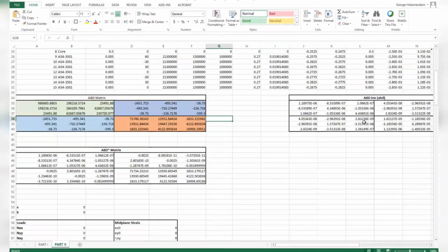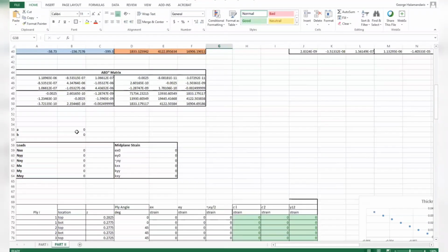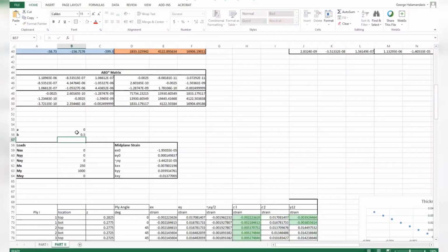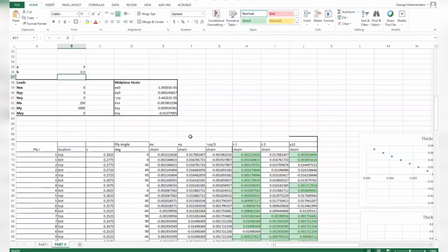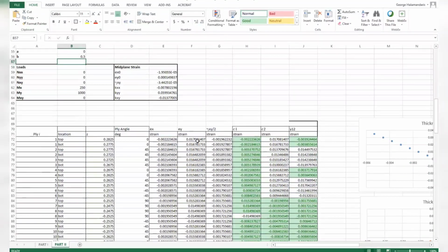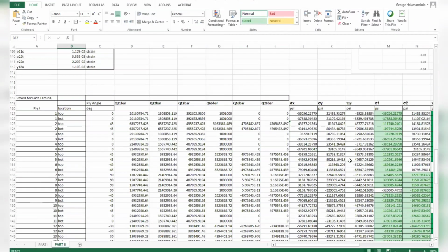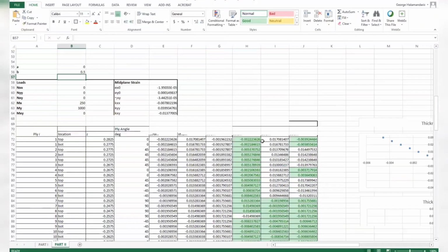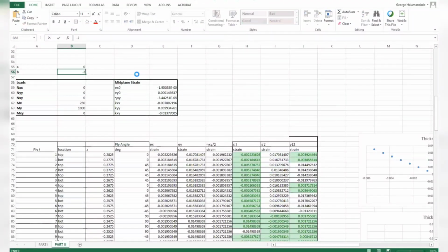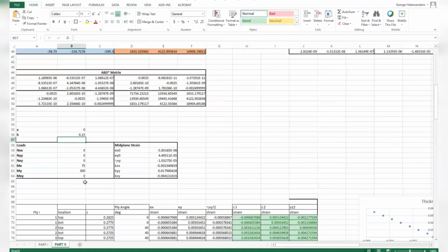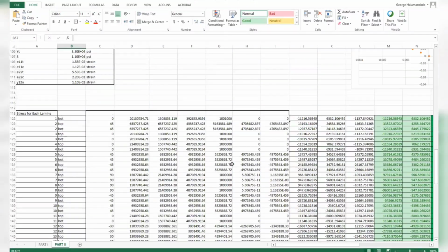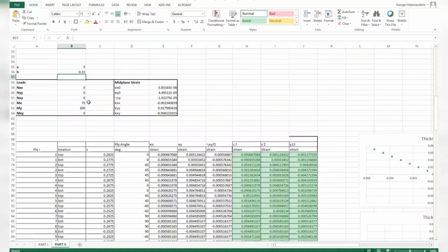Again, following this workflow, I have an ABD inverse matrix. With some load, I now can have midplane strains, which you can use with the relationships discussed prior to find ply-by-ply strains and then rotate them into their coordinate system, and then same for stresses. So one thing to note here is that with core, you can accommodate much more load. So again, it would be following that same workflow.